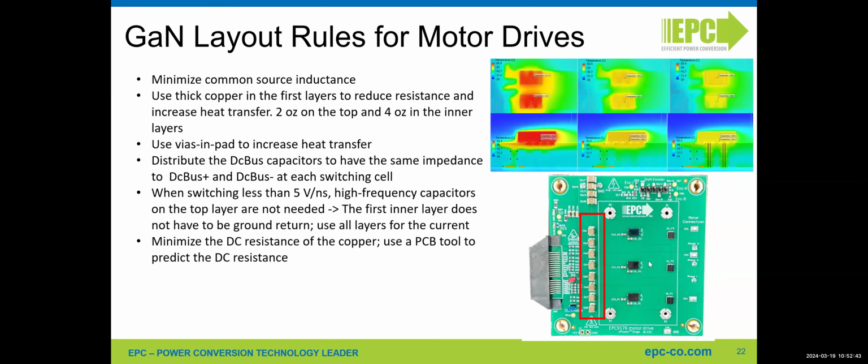I agree the space can be reduced a lot, and we will be designing a similar circuit in the future with smaller dimensions. Obviously, what is the trade-off? If I reduce the dimension of the copper, then I will have lower current capability of the inverter. It really depends on how much current I want to drive.